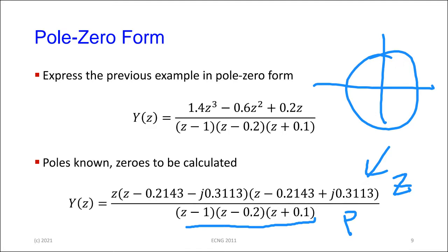So for instance, this is Z equal to 1, so that pole is right on the unit circle. This one is mod Z equal to 0.2, so that's inside here. This one has a modulus equal to 1, so that is outside, inside of here somewhere. So you could see where the poles are, inside or outside the unit circle, and so on. You're going to use that a lot when you do controls and advanced controls, if you are going along to do those things.